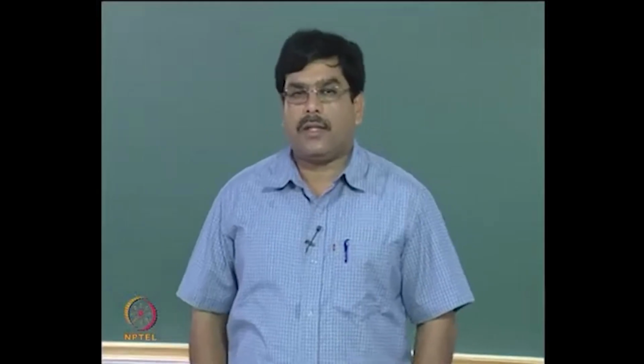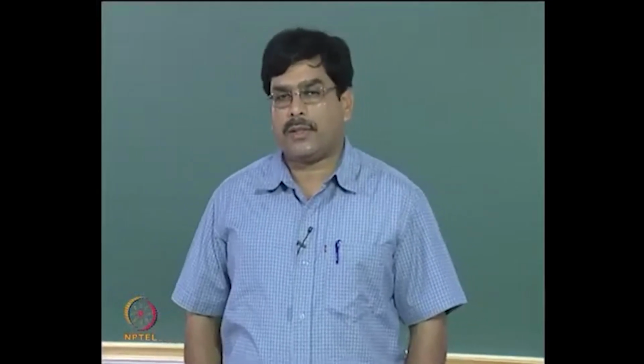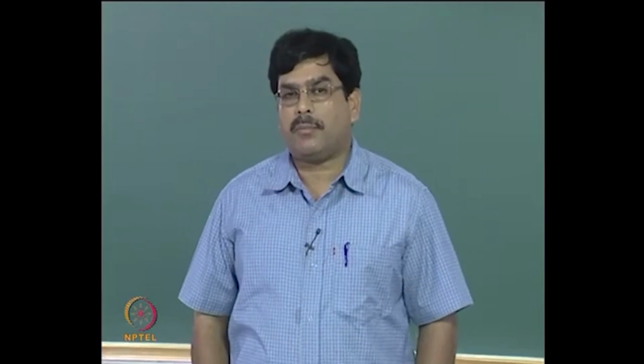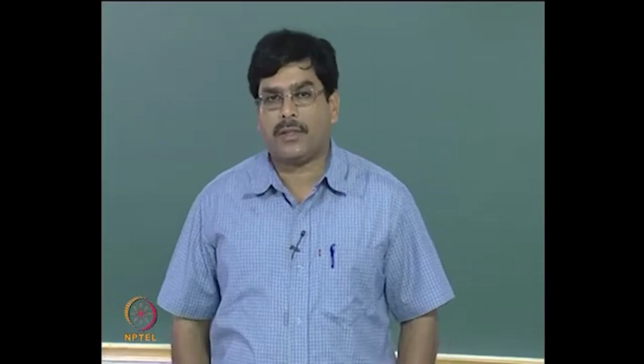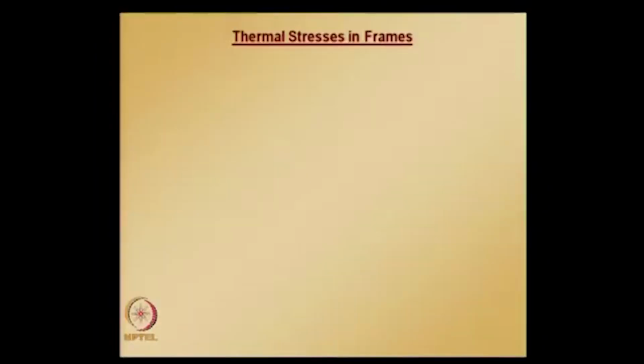In the last class we have seen how to solve 2D plane frames. Basically, a plane frame or even a space frame is a combination of several effects. If it is a 2D plane frame, it is a combination of axial force effects and bending effects, and we will see later that if it is a 3D space frame, even torsional effects will come into the picture. And so when we are solving a plane frame problem, assuming small deformation conditions and assuming all these effects to be uncoupled,